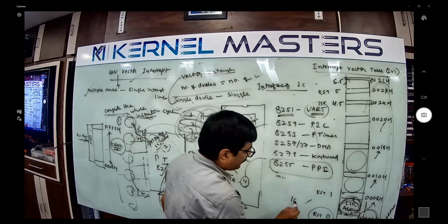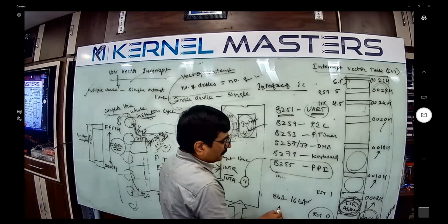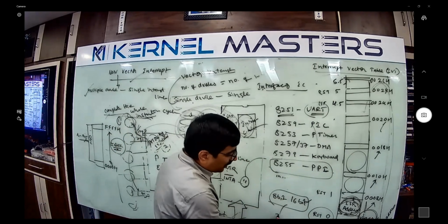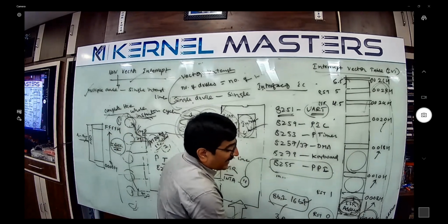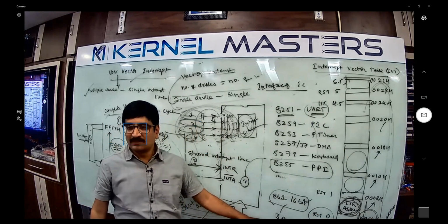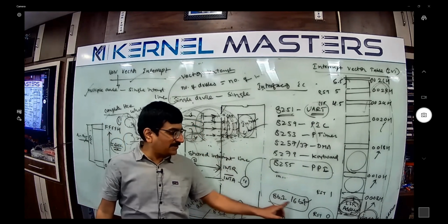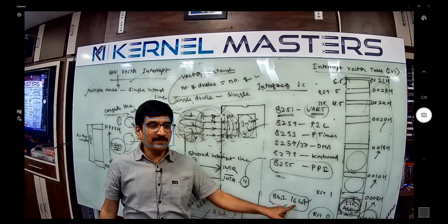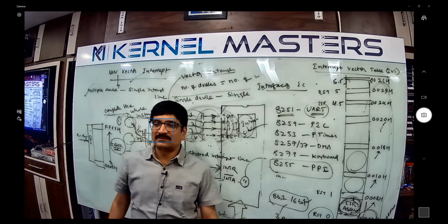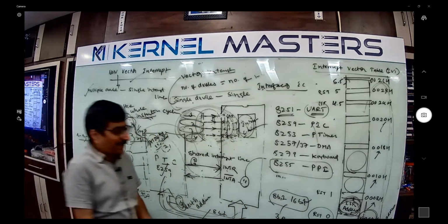Okay. Call instruction is there now. Call instruction opcode is 8 bits only. Total how many number of bytes? Bytes I'm asking. 3 bytes. 1 byte equals how many bits? 8 bits. 8 plus 16, 24 bits. How many bytes? Total, 3 bytes. 1 byte is the call instruction.